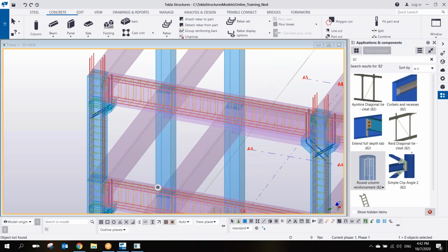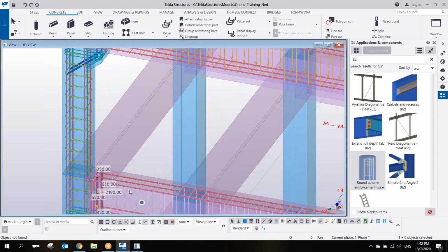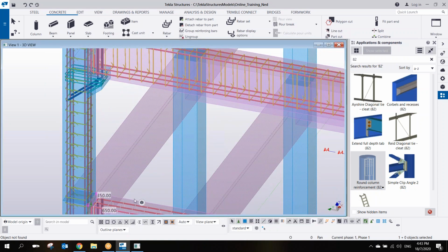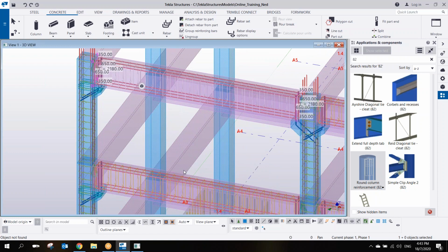Does the rebar act like a component? If you're talking about this rebar, when I copy it from this beam to another beam, it will not work as a component. It's a simple copy command. So this one doesn't relate. Once you copy to another beam, the relation is not there anymore.